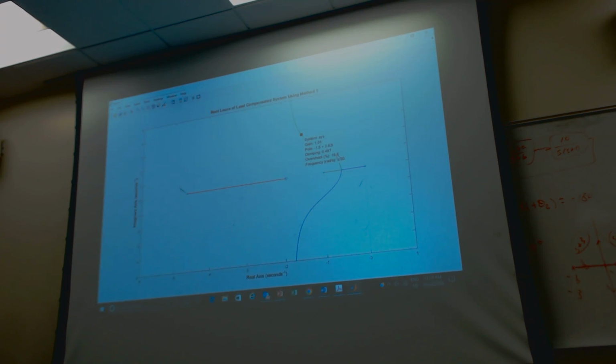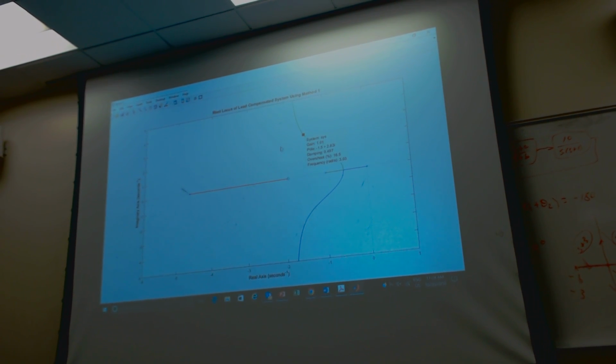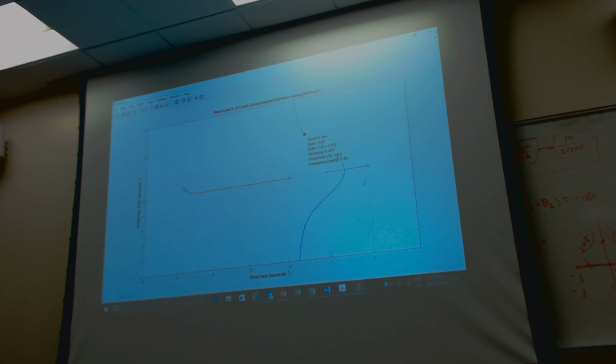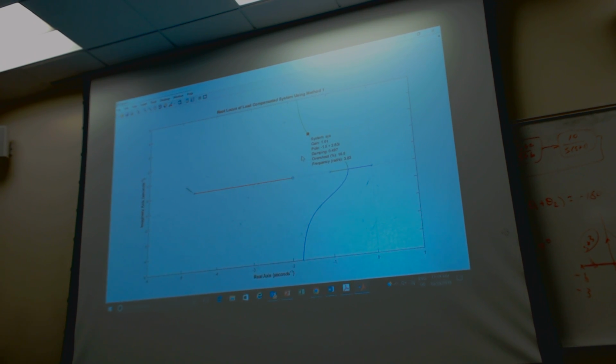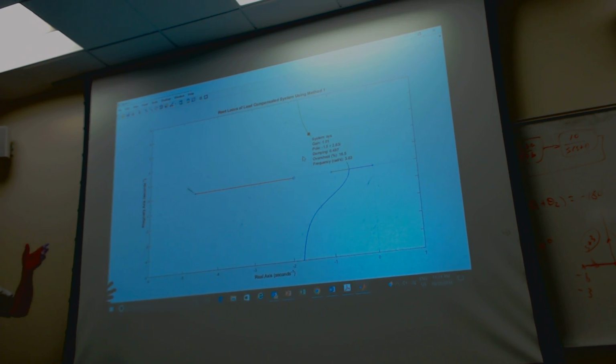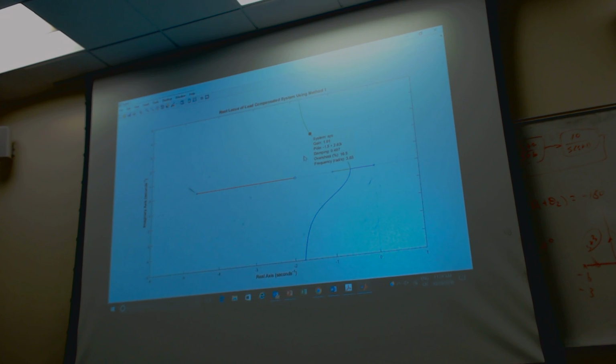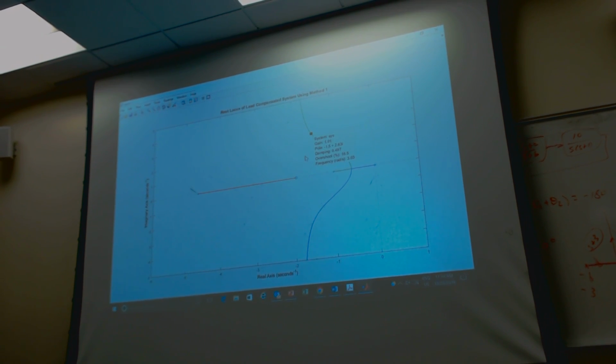You get the same percent overshoot for this? Oh, what do we have? They were both 16%. Is there any benefit to using one of these over the other? Yeah, there is some benefit. This is a step response, by the way, that's what we're looking at. In terms of the steady state ramp error, method one here can reduce the steady state ramp error. So that's one advantage of method one over method two of pole zero cancellation.